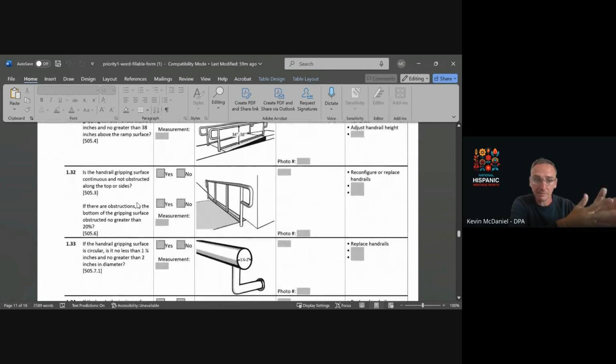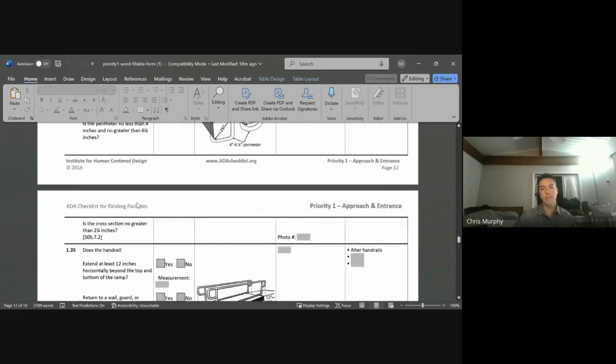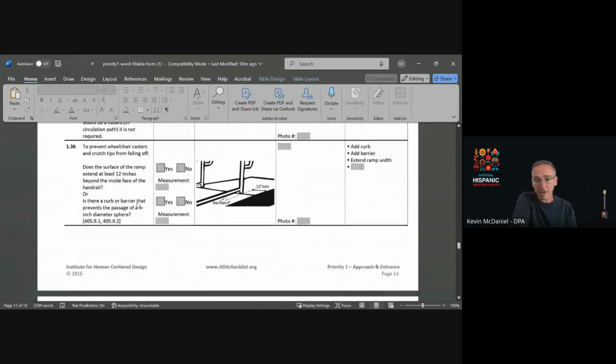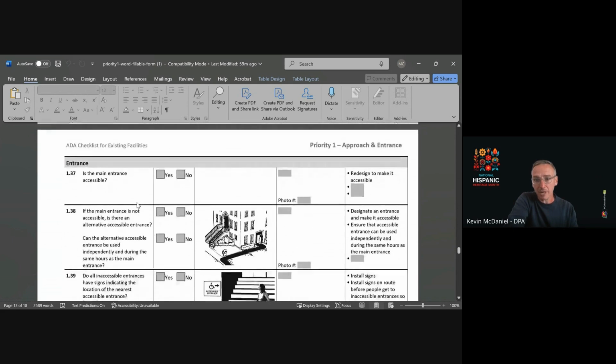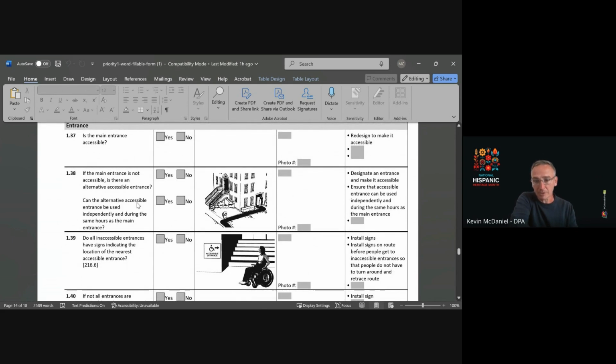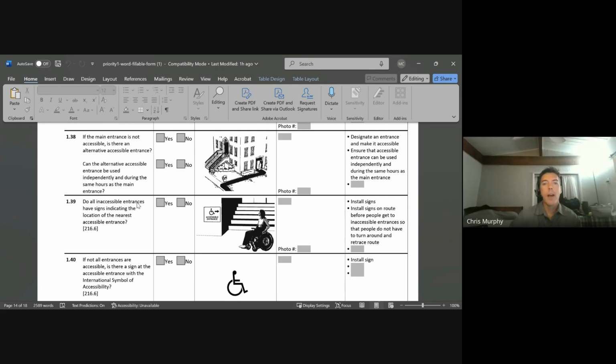Just making sure I read everything on this paper right. Do they have an access route that also connects from the access lane to the front door? So is there a path of travel from the disability parking space in the access lane to the front door of the building, and is it 36 inches wide? I really hope that the folks who don't do facility stuff can leave with 3 or 4 takeaways so they can go out and do a check. Absolutely correct.